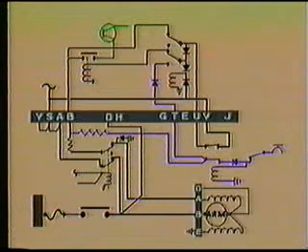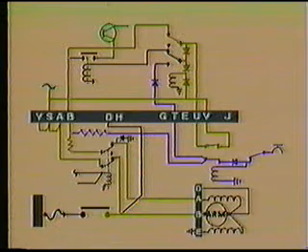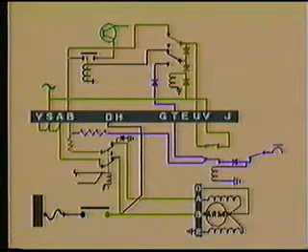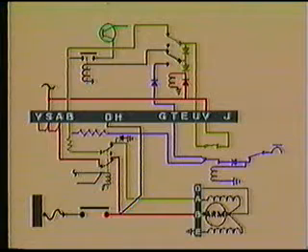When we move the generator switch to the reset position and the airframe installed reset relay closes, several events take place very quickly. The closed contacts of the system reset relay provide a path for B lead output to be connected directly to the field via the A lead. This immediately causes the generator output to begin rising.